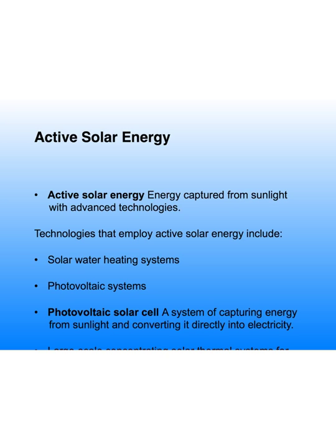All right, so active solar is what we typically think about, right? Of course, we were doing a lab that used passive solar, but active solar is capturing sunlight with advanced technologies, right? It's what you normally think about when you think of solar power, right? And that's going to be photovoltaic systems, solar water heating systems, right? And it's important that you know that a photovoltaic cell can be simply called PV cells, right? Capturing energy from sunlight, converting it directly to electricity, and this is usually using some semiconductor like silicon, right?